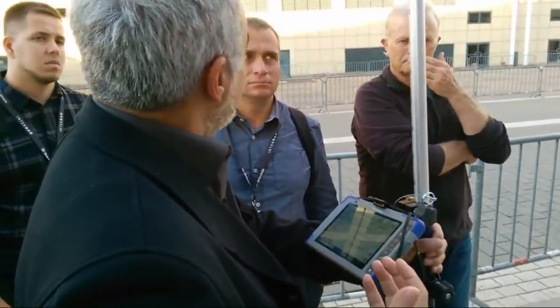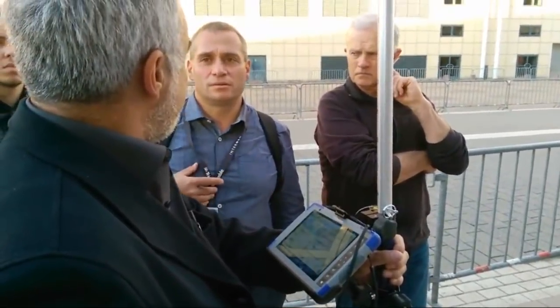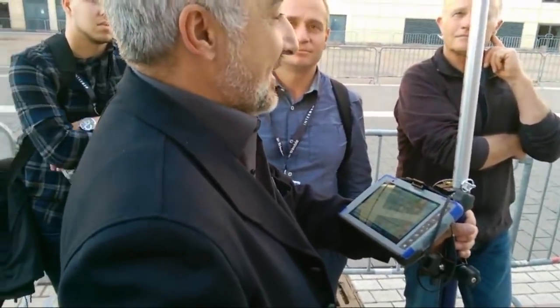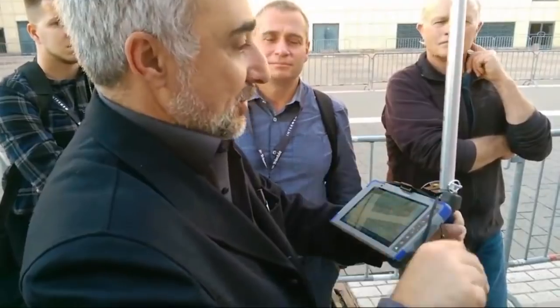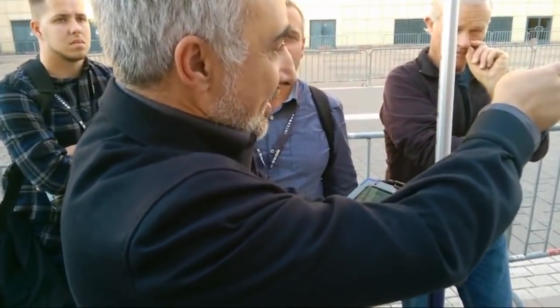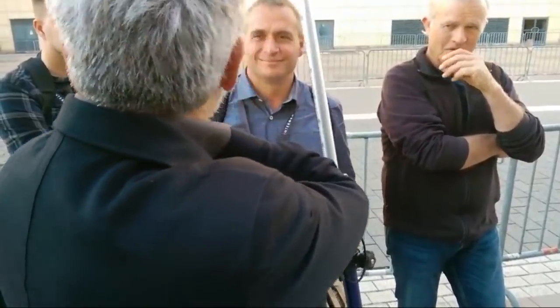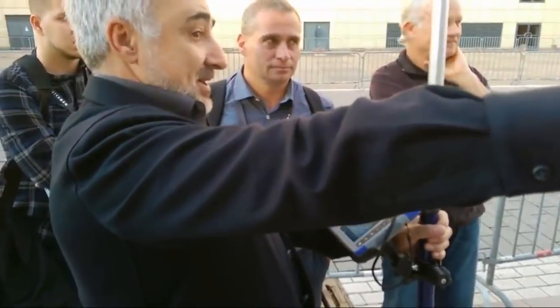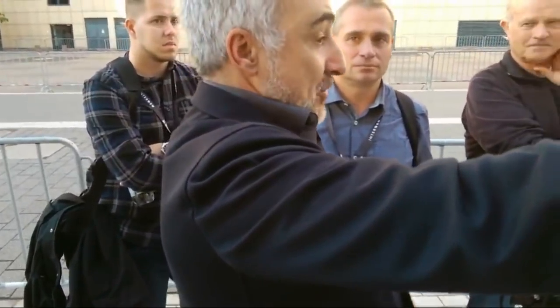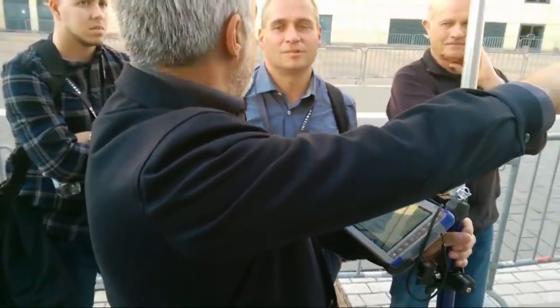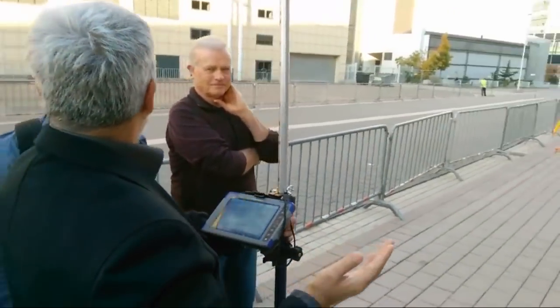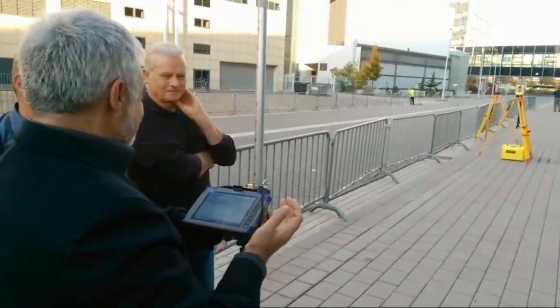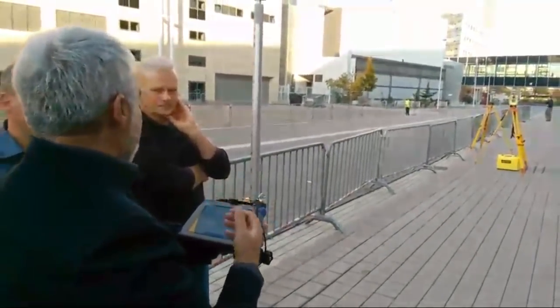So you get a lot of confidence. And sometimes there is trouble with the reflector. Many times I was on a road doing a search and locked onto a motorcycle driving through the road. Those things happen. Or other prisms, as it happened with me before, right? I knew it was not right because I couldn't see the instrument, but if you don't see it, it says locked. You say, oh, I'm locked. I'm happy. Measure. Okay, so hybrid brings a lot of good things.